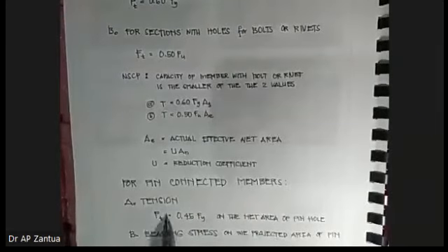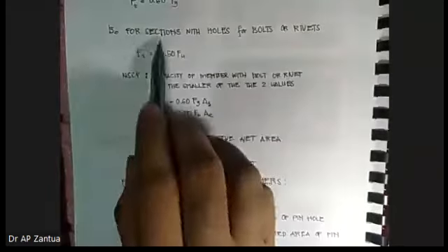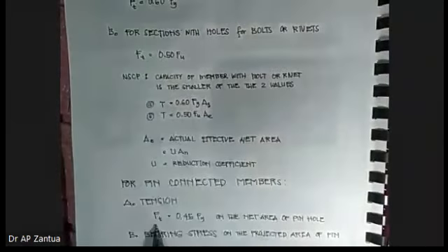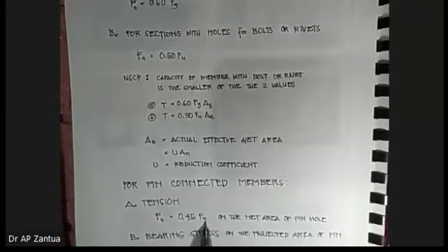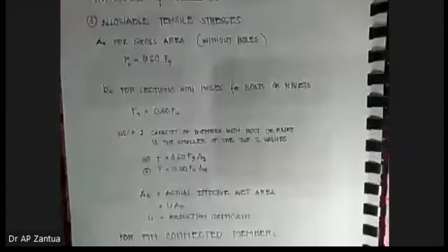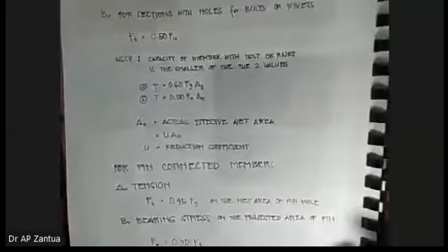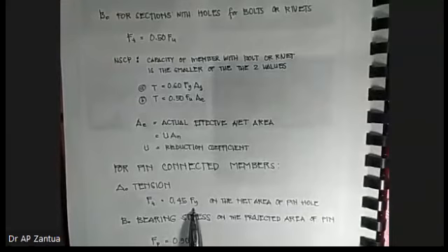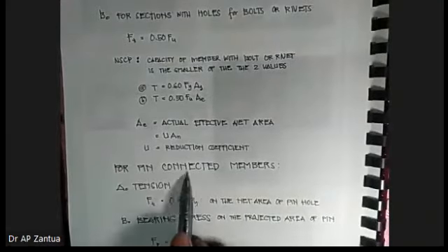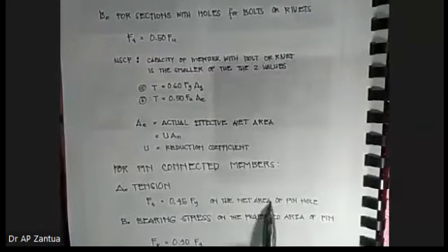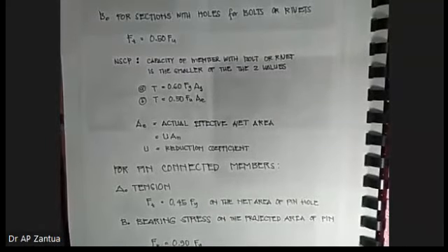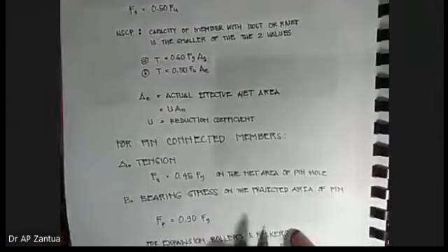This is actually stress, FT, same is true with this, FT, in terms of MPa, equal to 0.45 Fy. A while ago it was 0.6 Fy, now it is 0.45 Fy. That is for pin connected members on the net area of pinhole. Take note, we will have an example of this.